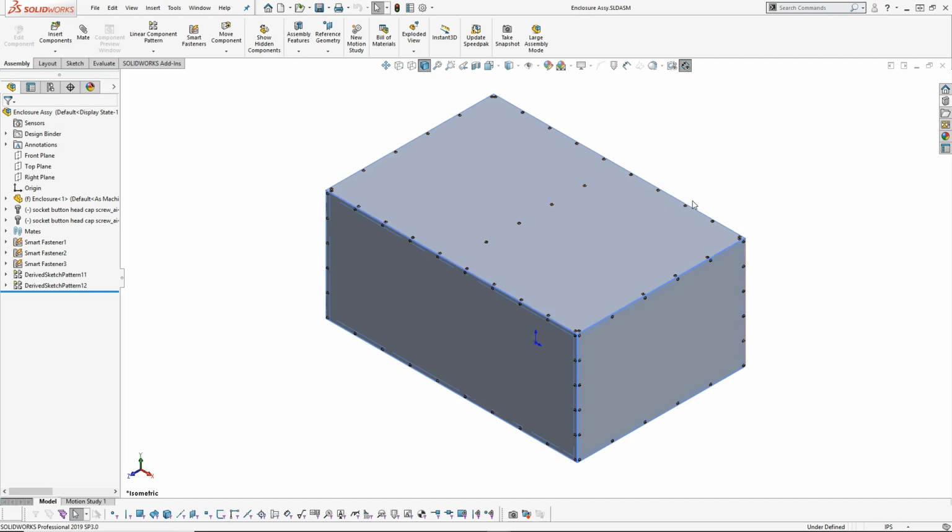Well, I know the front and the back are identical, left and right are identical up to this point, but if I have to have a pass-through for electrical and a port for hydraulic and air, pneumatic, or any other power supply, ventilation, that kind of stuff, these could very quickly become unique items. So the downside to the multi-body part is, I don't think it's possible, well, it's not going to be easy to create an exploded view.